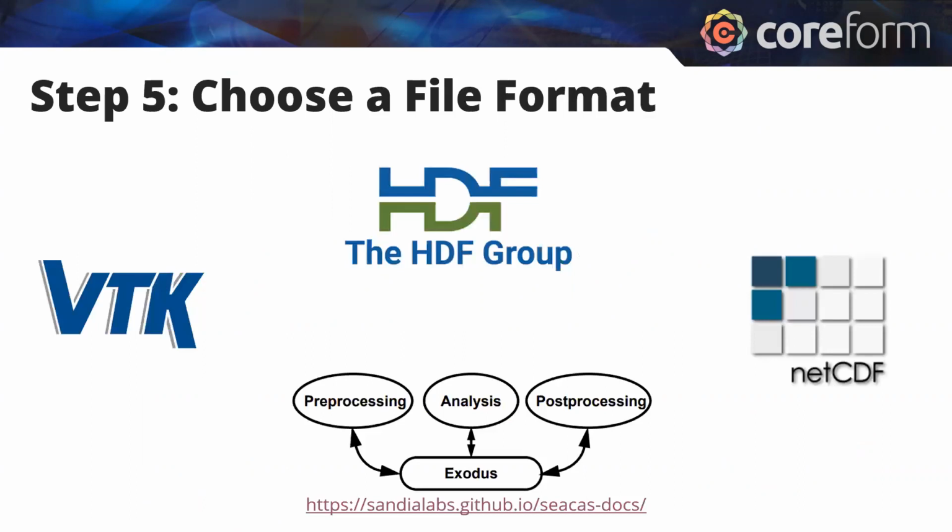Then I recommend choosing a file format. My opinion is that if you look at tools like Cubit and ParaView, as well as the solvers, they oftentimes allow for a variety of different input files to be used. I do recommend that you try to gravitate towards the input file that has the most native support in the solver you're picking.